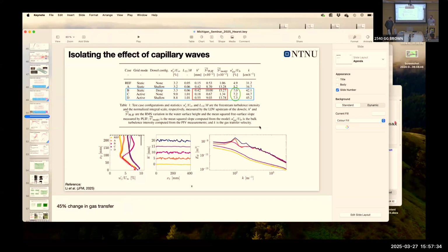Any last quick questions? Quick one about that lift surface measurement. You're looking through the window of your tunnel, you have your laser plane somewhere: how 3D can it be before you can't actually resolve the interface where your laser plane is? We're having fun with that right now in the experiments. Generally we look at it from above, not directly above but from 15 to 20 degrees, and we calibrate out that we're looking at an angle.